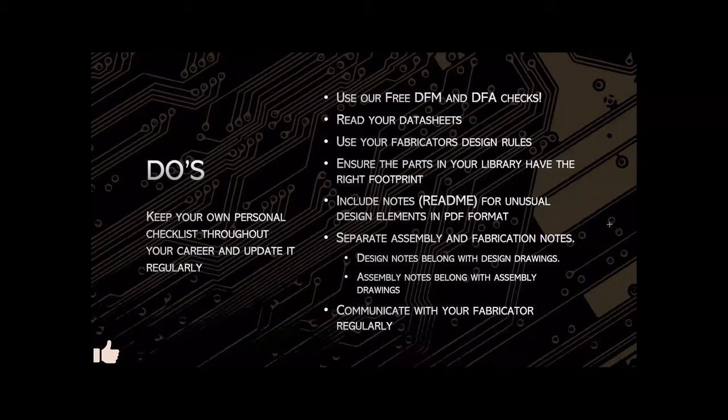Elijah, do you have anything to add on your end for the fabrication side? Yeah, definitely. I'd like to, again, just emphasize that last note of communicating with your fabricator regularly. If you are using a new fabricator, or maybe you just haven't contacted your fabricator, get in contact with them, know their design rules, and the better relationship you build with them, the more they're going to be able to know what to do with your design sometimes.